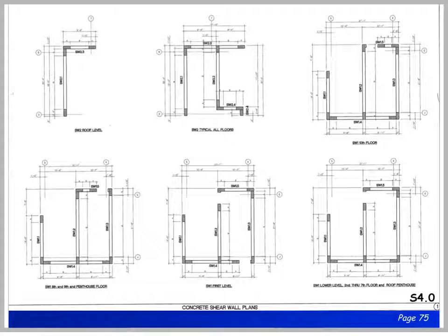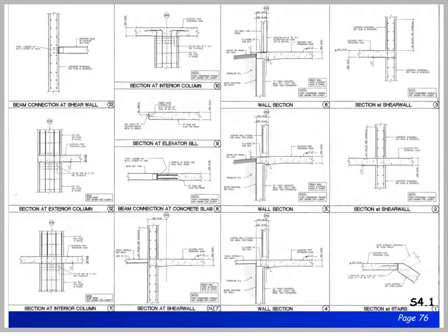Later in the set, the shear wall schedule will relate back to these plans for additional information for the shear wall rebar. Note how the engineer relates back to the floor plan and elevations with the column line references. As we move on up through the building, we continue to see additional details. The details have phantom architectural delineations on them to better show how the building goes together.